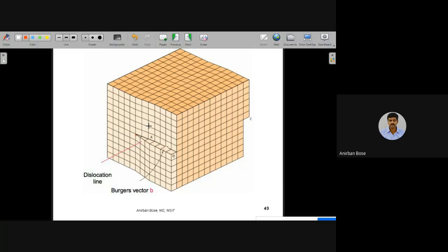And that shear effect will definitely be around that line, because this region will give some resistance, because these bonds are actually not cut. So this part is trying to give resistance, so that will try to defend the shear. So the shear stress will be developed in this region. Here all the bonds are cut, so this portion will not feel any shear. So where will it feel shear?